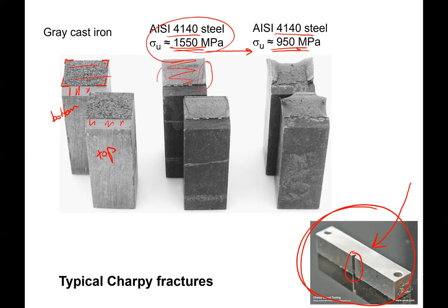You're just getting some plasticity there on the edges. You can see it here on the other side of the sample. And when you drop the ultimate strength and increase the ductility, you can see a lot more ductile tearing on that sample. So as ultimate strength goes down, your ductility measure, percent elongation, goes up. We can see that right in the samples.